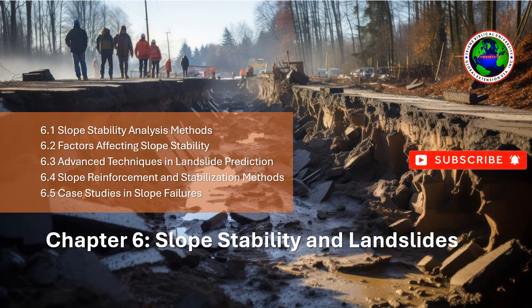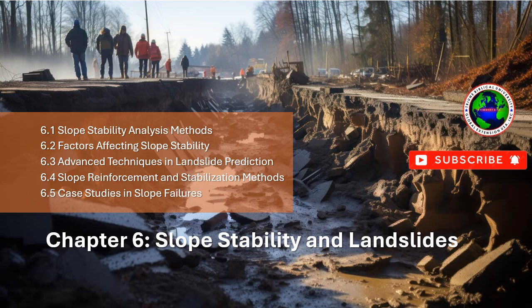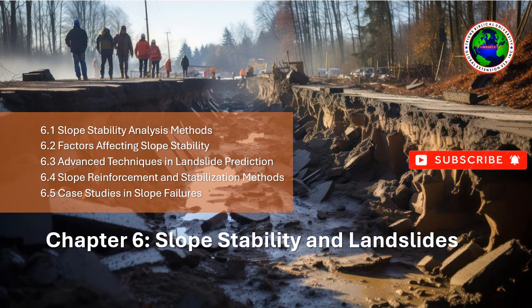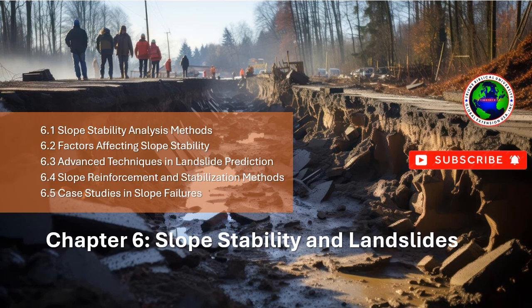6.1.2 Finite Element Method, FEM. The finite element method, FEM, is a more advanced numerical approach that divides the slope into smaller, discrete elements, allowing for a detailed analysis of the entire slope system, including its geometry, material properties, and boundary conditions. FEM is especially useful for complex slope conditions where traditional methods, like LEM, may not provide accurate results. Key features: